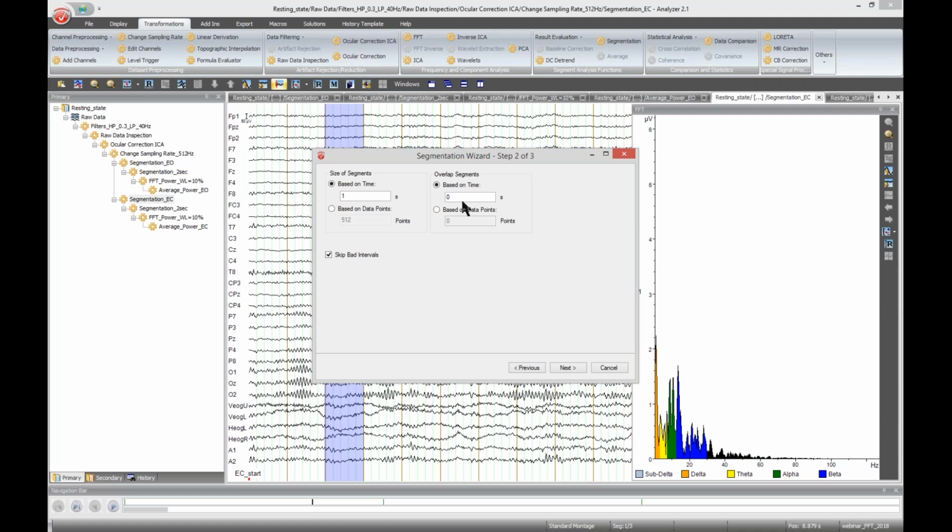By subsegmenting your data, you assume that this portion of data is stationary or quasi-stationary. And this assumption is quite relevant for FFT, because in order to interpret your result at the end, this criterion should be fulfilled. So that is why it is necessary first to segment your data and then apply FFT on it, and then at the end average.